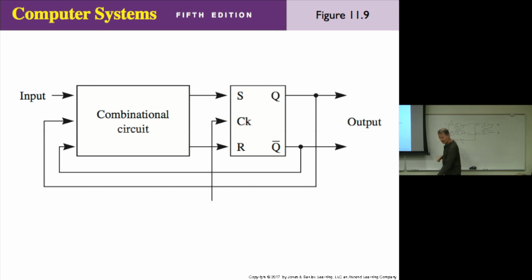But I want everybody to understand. Does everybody understand what we need to have happen? We need to have the first change in the flip-flop, that very first change, captured, and not let any external feedback go through the combinational circuit and change it again, until the clock pulse ends.